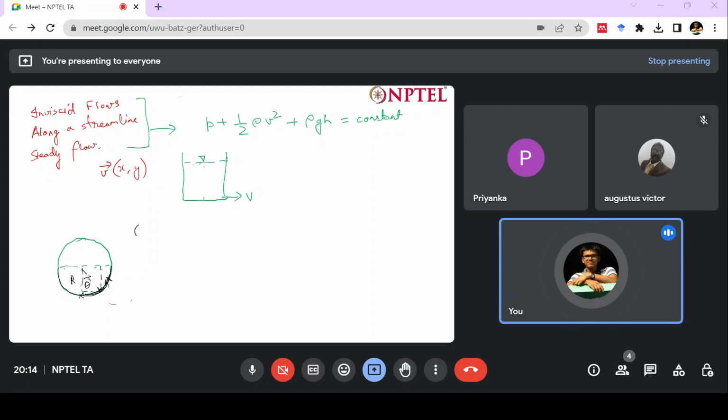So your excess pressure apart from the gauge pressure will be this, rho g r cos theta, correct? Now this pressure is acting this way, and at some other point it will be acting in another direction depending on your theta, since it is acting normal. But you would want in your force only in certain direction, right? Are you following? Am I answering your question?